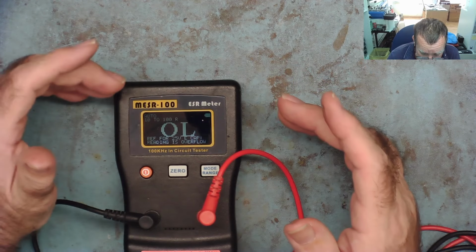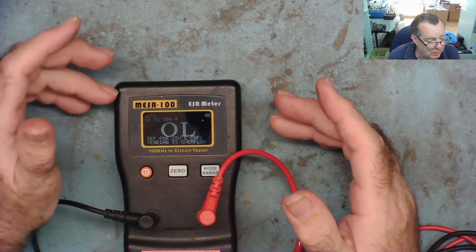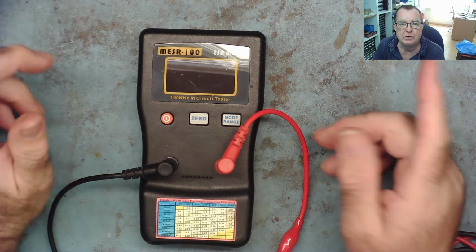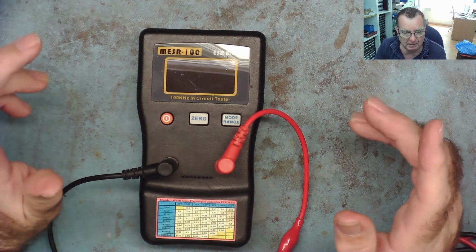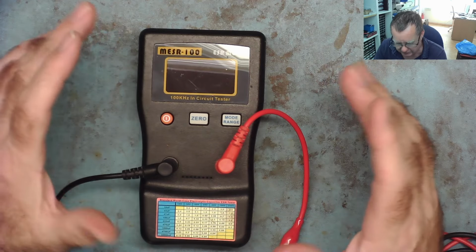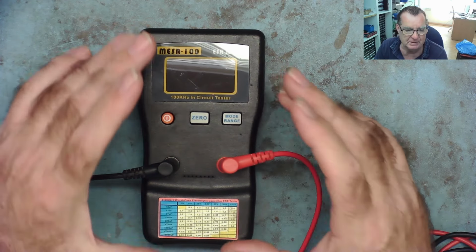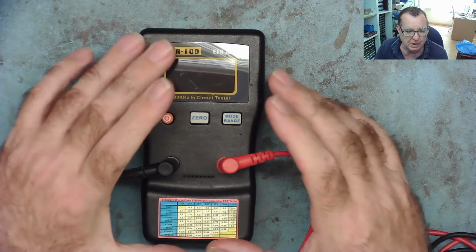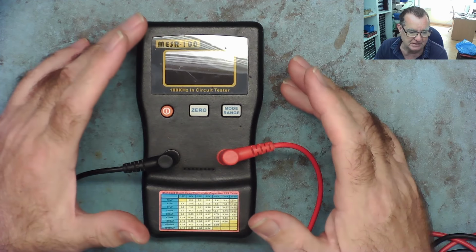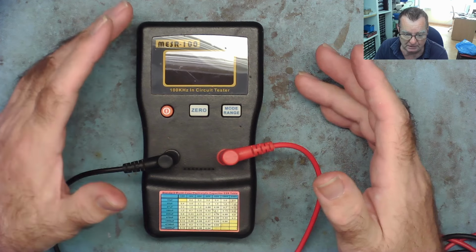But this can do quite a bit more than just test capacitors. So let's have a look what else we can do with it. There's another type of component which reacts differently to AC and DC, and that's an inductor. So can we use the ESR meter to measure inductors? The answer is yes, we can. So I'm going to show you now how to use the ESR meter to test an inductor to see if it's the correct value, and how to measure the value of an inductor where the value isn't marked on it.